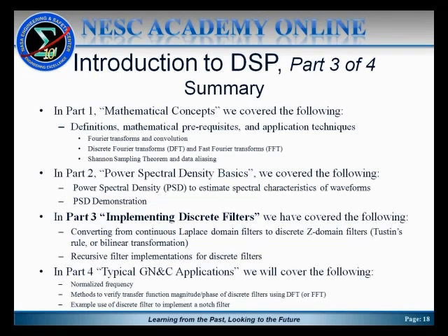We'll also show, as I mentioned earlier, one of the common problems with using discrete filters is you really need to understand how the discrete filter has been defined, and especially if you're working with someone else, if they give you coefficients for a discrete filter, the first thing you probably ought to do is verify the transfer function magnitude and phase using techniques that I'll show in the next part of this presentation before you actually implement your filter. That will save you a lot of problems in the checkout of those filters.